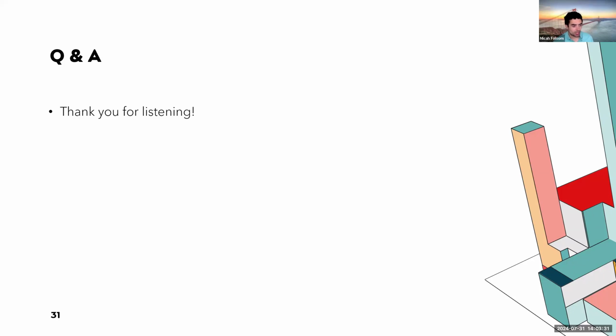For shielding, I mentioned, you may want to use a specific physics list that is more optimized for that. I didn't go over this, but Sean talked about things like variance reduction, weights, which are way more useful for shielding, right? There are a lot of physical and geometric pathways for the particles where the probability of them happening is virtually zero, so there's no reason to actually send a particle in that direction. You can do that in Geant4.